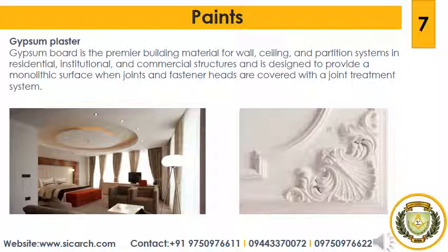It sets by natural process of crystallization, hence it can be applied with ease and without wastage. It sets with little change in volume and with negligible shrinkage or drying. It shows good adhesion to the fibrous materials. The plaster of Paris is used in artwork, pottery, dentistry and in surgery for the shaping of fractured bones. So that's all about gypsum plasters.